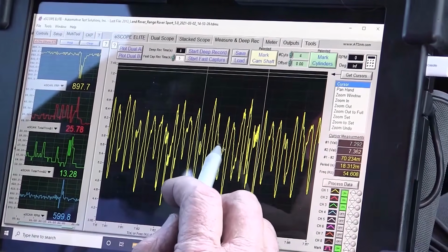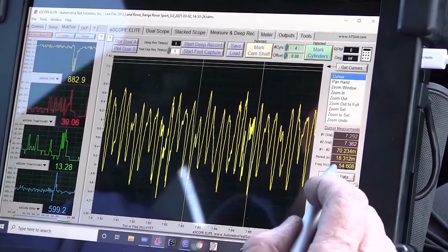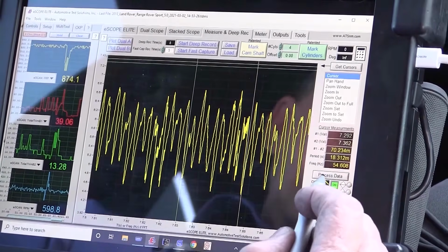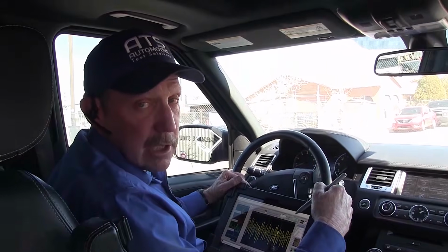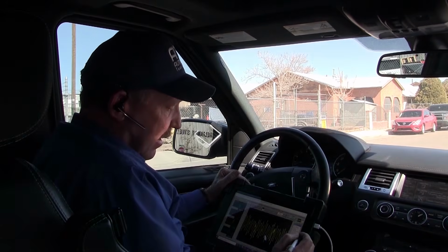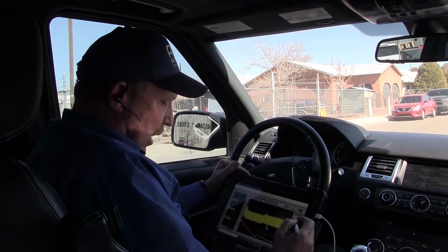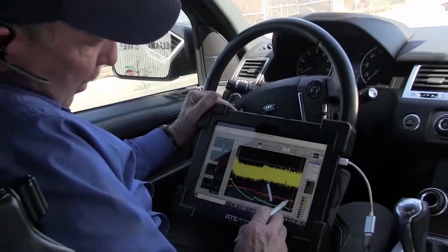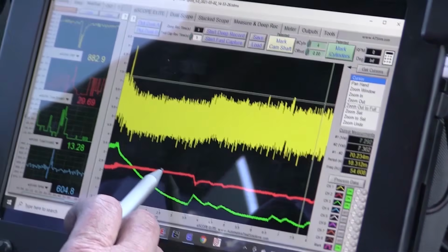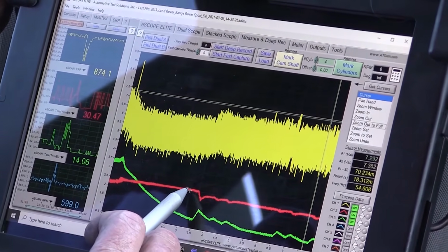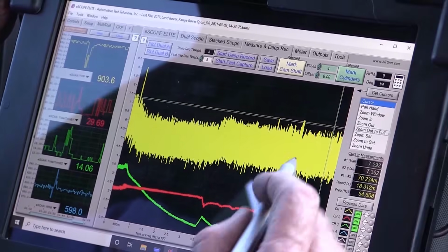1, 2, 3, 4, 5, 6, 7, 8. 54. It's not changing. The pump is not speeding up and slowing down, but the pump is staying very steady. And we can also see that in the pressure. So the low line pressure, I mean, look at when this dropped. Look at how steady that is. And we already saw that the command during this point isn't a problem.